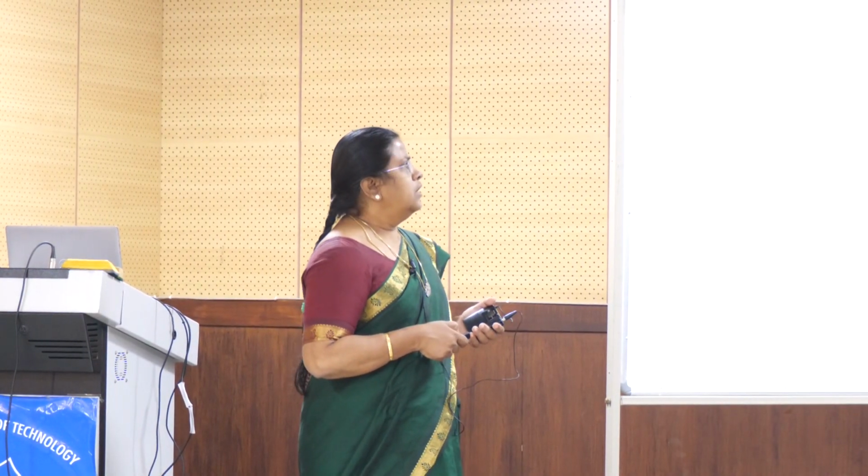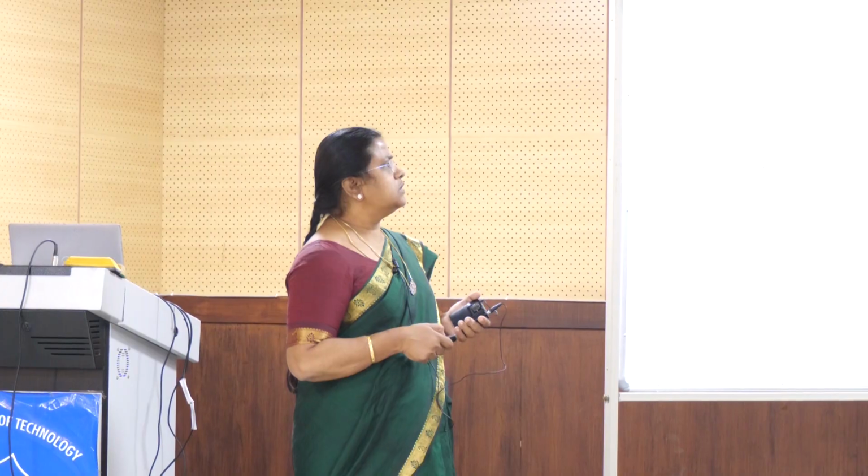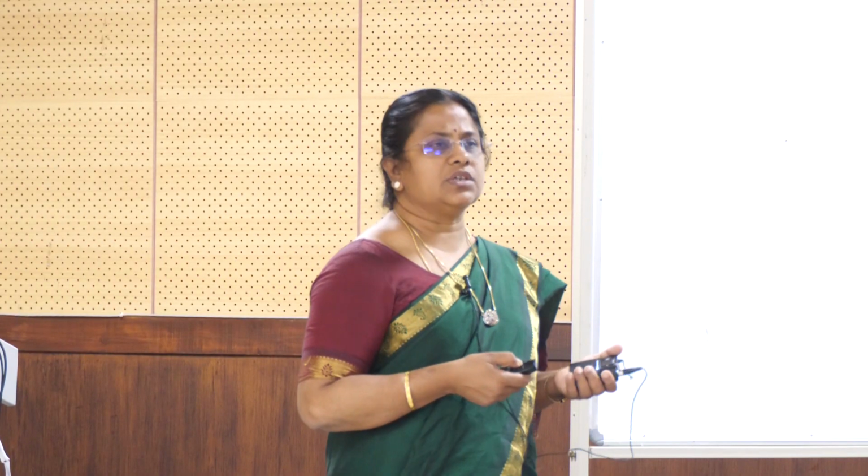Okay, now let us come to our topic, the finite volume method. It solves partial differential equations and calculates the values of the conserved variables. Here the conserved variables, if I take the Navier-Stokes equation, are velocity and pressure, across the volume. The advantage of FVM over FDM is that it does not require a structured mesh. In unstructured mesh also it performs well.